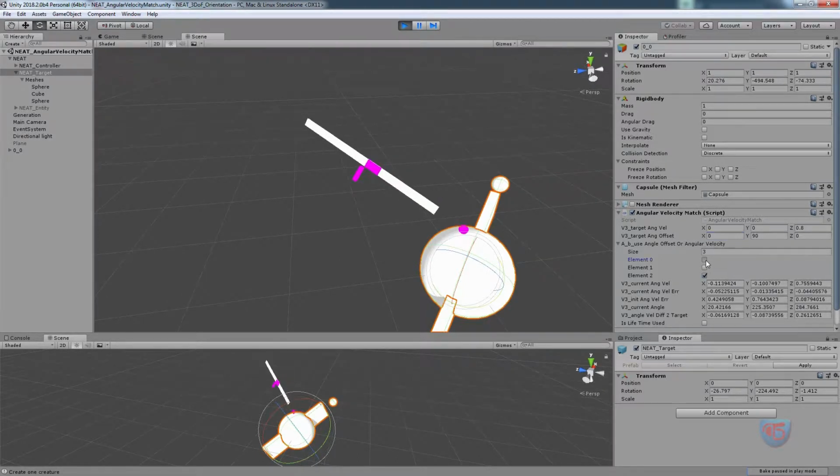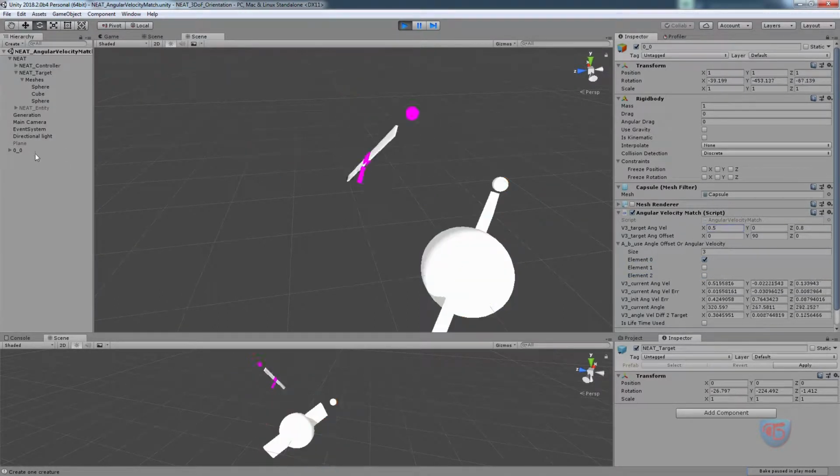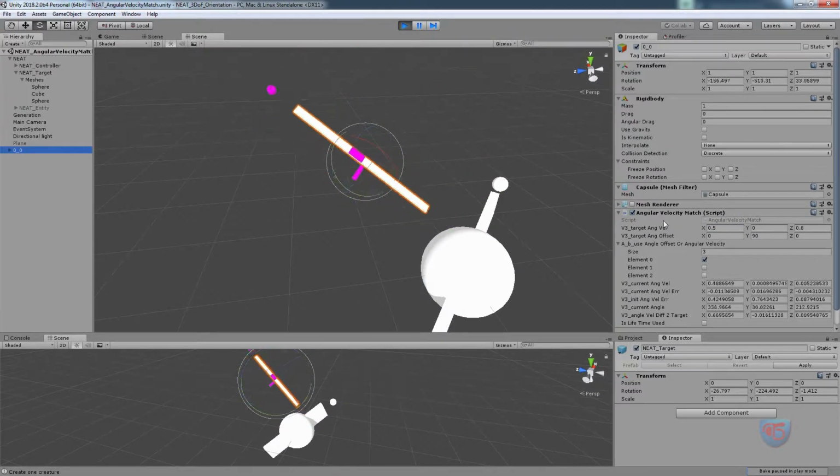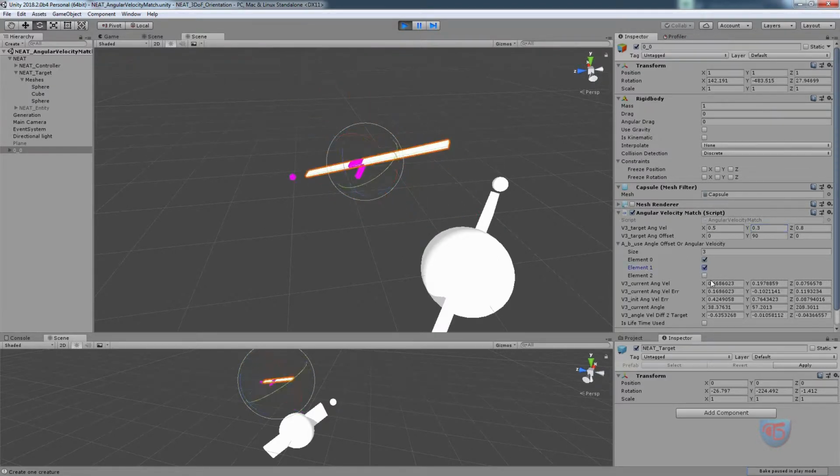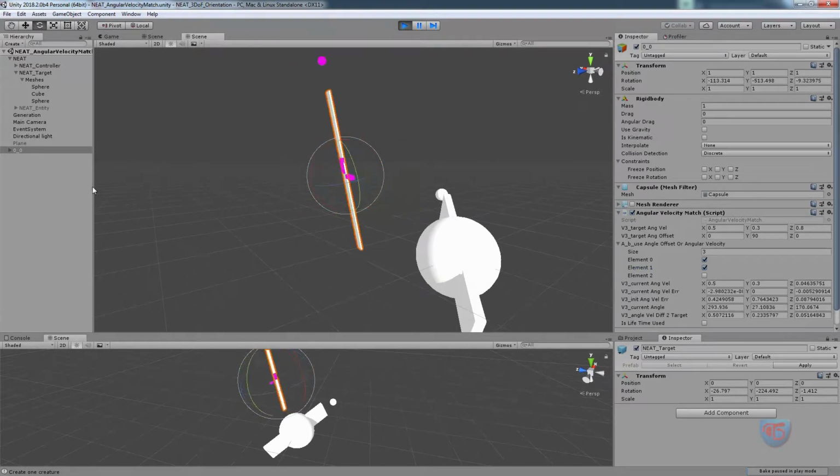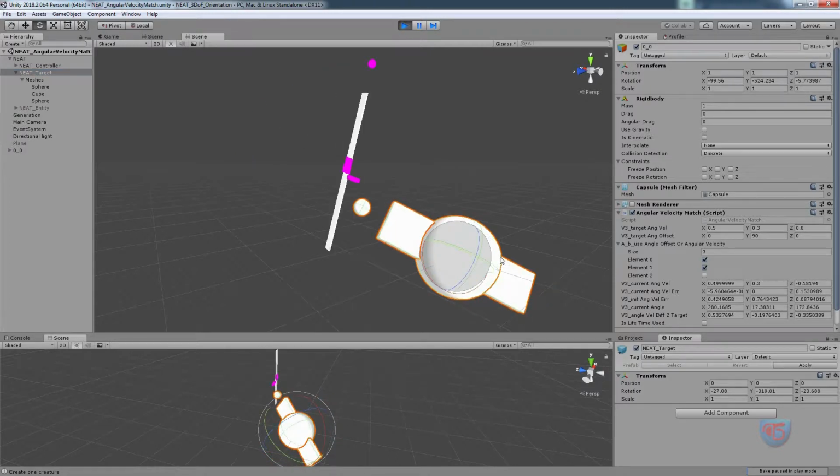Or maybe I want to spin along the x-axis instead of the z-axis. I'll add my spin, so now I'm rotating on my own x-axis. Let's say 0.3 if I want to have x and y-axis, and yet be facing the z-axis the same. Of course now it's a bit difficult because of the general rotation, so it might get a little crazy.